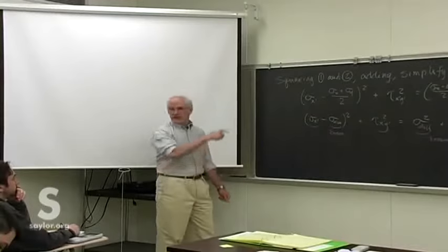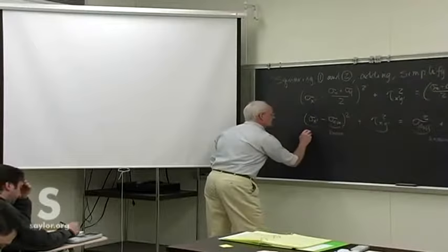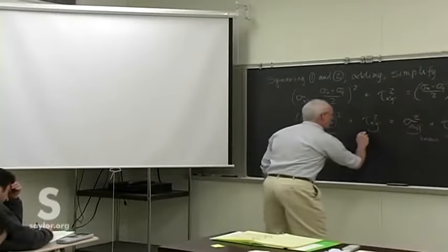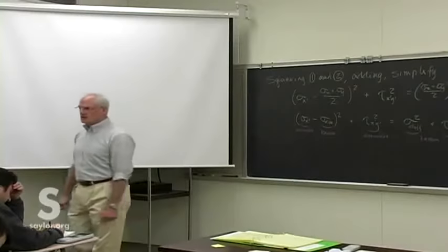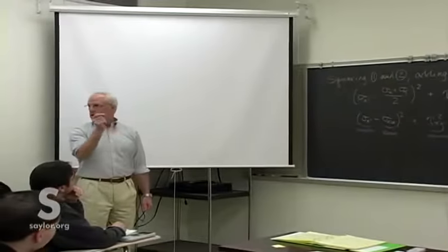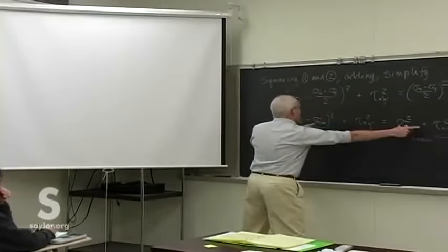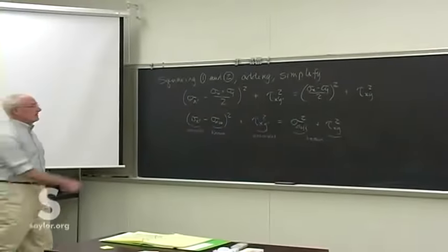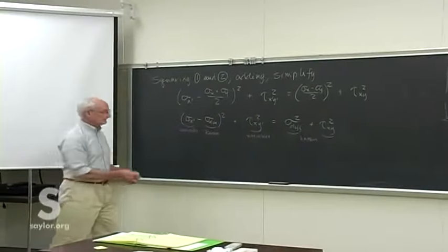Those are functions of the angle chosen, which can be arbitrary, but won't necessarily be very soon. So we'll call those variables. So I give you a problem like we opened class with. You figure out the stresses in the ordinary orthogonal directions, horizontal and vertical. That sets these three values that I've marked known as constants. Then you look at some other angle, and the other two terms then become variables.